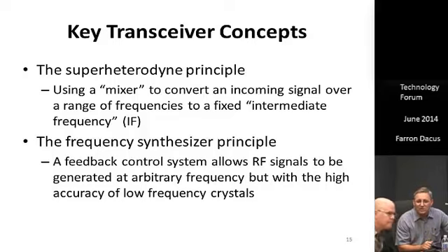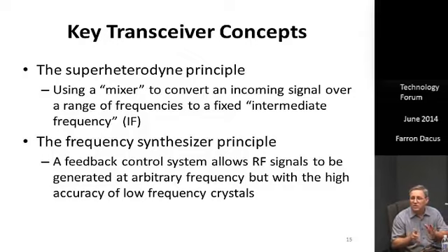And that's what a Superhet does. It does it two ways. First off, it converts the incoming signal to a fixed frequency where you can use an extremely good filter, a ceramic filter or a crystal filter historically, though these days it's often a low IF filter on die or digital signal filtering. But in addition to it being some type of physical process that allows narrow bandwidth because it's fixed, it's also converted down to a lower frequency. And at a lower frequency, for any given Q, the bandwidth is proportional to frequency. And so that lets you get that bandwidth down.